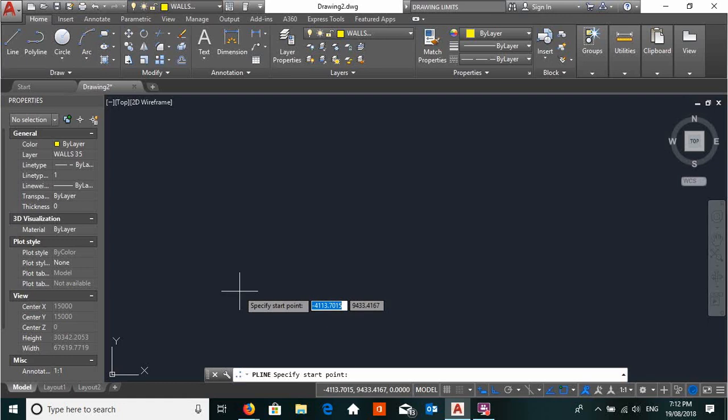So to start the cavity, that is, to offset for the cavity, polyline we've chosen. We're going to start by absolute coordinates, and we're going to type that in. The blue is prompting me where to start my first point, so I'm going to just type in 6900, and lock that in with the comma, and now I'm doing the Y coordinate of 6,000.